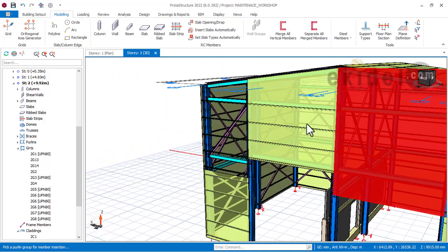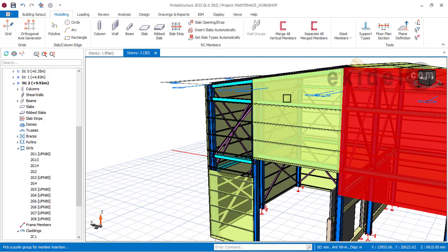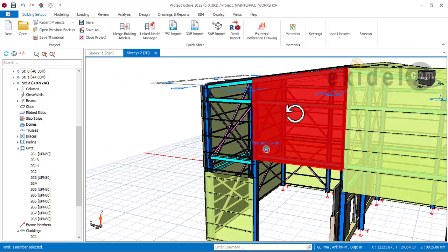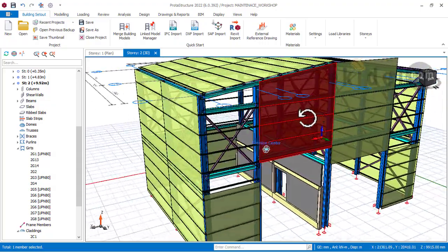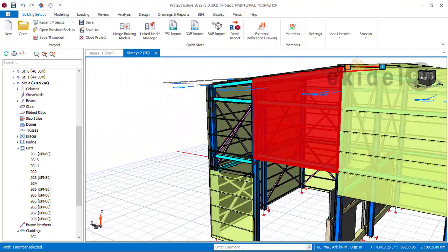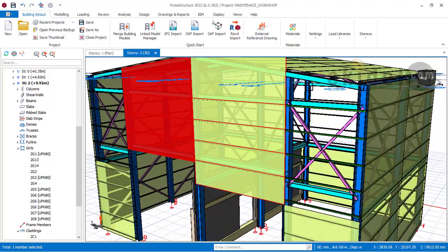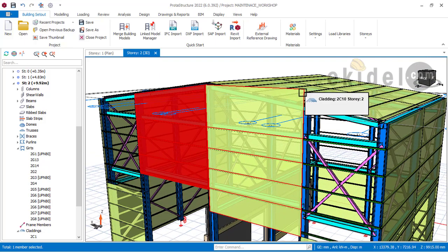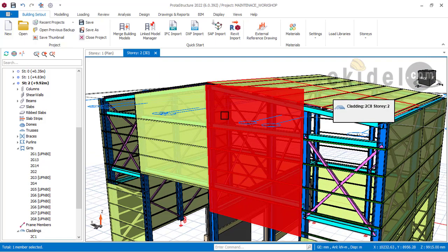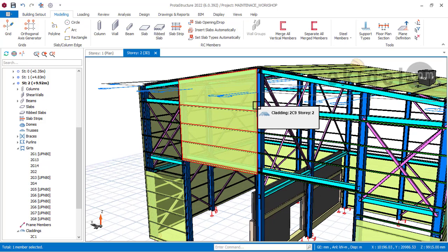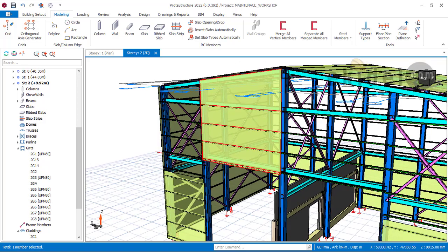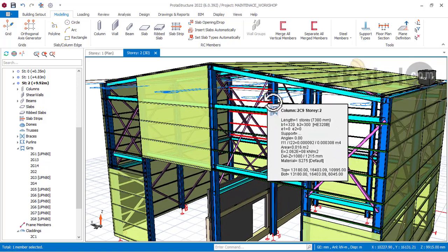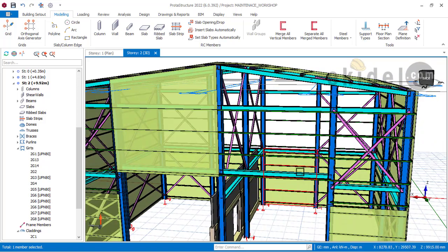So you can see that this other one here is perfectly placed because we used angle, and it is also flushing with this. So I'll just remove this and then use the other angle. Whenever you are working with angle, know that there is what they call anti-clockwise and also clockwise. This one that we did now is called a clockwise cladding, and this other one that I'm going to put on this side will be the anti-clockwise, which is just the reverse.